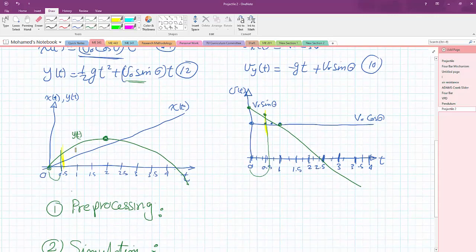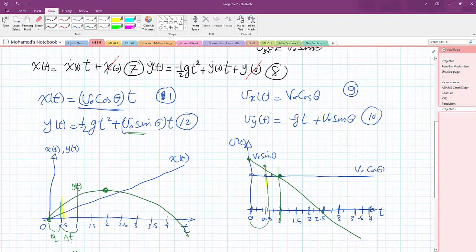So it will say at time equal to 0, we knew everything. We used the solution from this step to go to the next step. What will happen next? Now we would like to go to another time step. We would like to advance more. So we'll assume there is delta t, another delta t here, from here to here, another delta t from here to here. And we would like to compute the values at this new delta t. So what is going to happen? The solver is going to take the solution from this point and assume it will be the initial conditions for the new step right here. What do you mean by initial conditions? Remember, in this solution you need the initial velocity and the initial displacement.